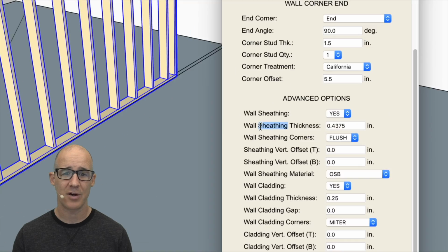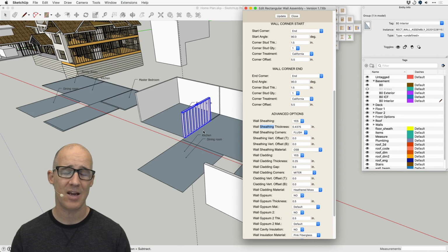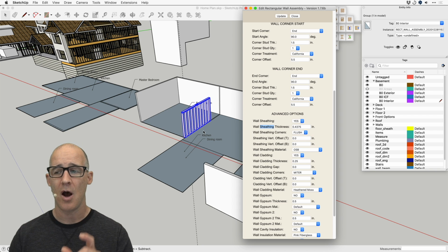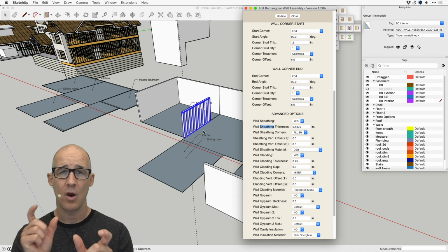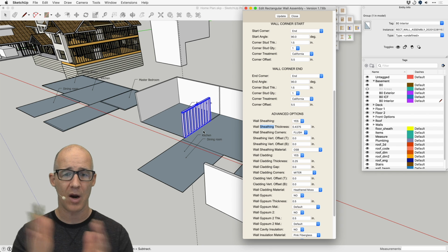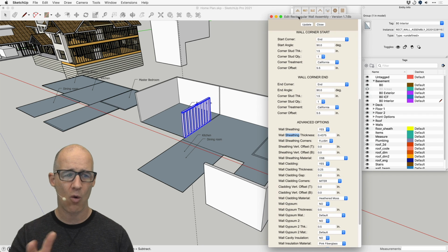In fact, we're going to learn that I am going to be using a ZIP system, which is an integration. It's an exterior insulation, but it's an integration of some insulation with the actual sheathing, with the water protective barrier, and how that actually keeps your house from basically getting wet and destroying over time. But that's enough about walls.